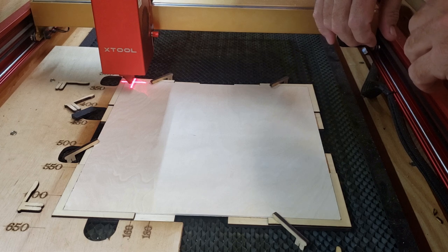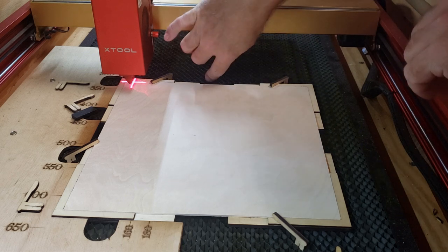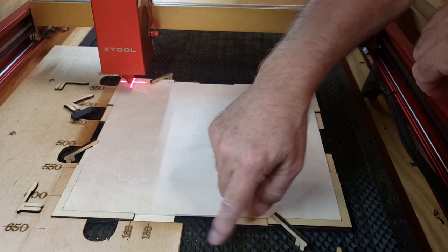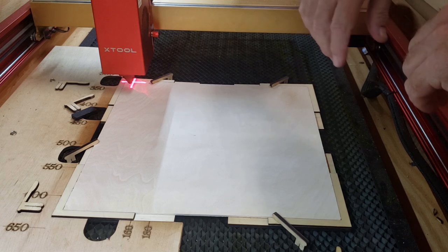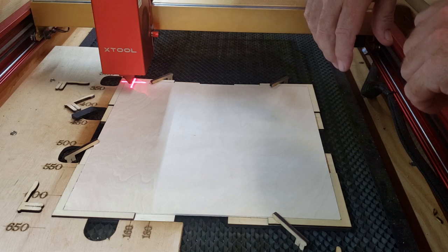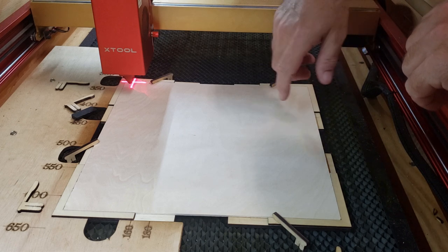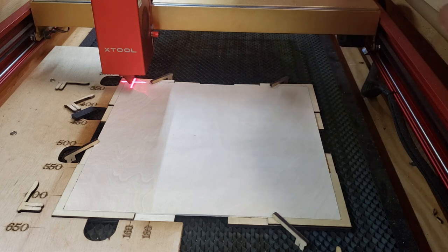And one of the things that contributes to a fire is pieces that get caught down in the honeycomb. So I try to clean it once a week with tweezers and with the shop vac, and try to get all that stuff out of there. But just be careful. So we're framed up and ready to go with the new piece of wood, and we'll send the code on over, cut this out, and see what it looks like.